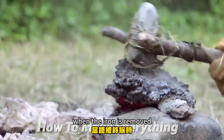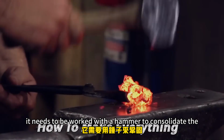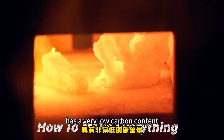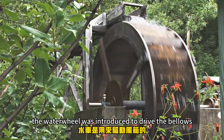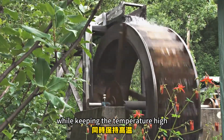When the iron is removed, it is in the form of this porous mixture of impurities and iron. It needs to be worked with a hammer to consolidate the iron, while the waste material is beaten off. The material left over is wrought iron, which, as we discussed before, has a very low carbon content. These bloomeries produce very small quantities of iron, especially before the water wheel was introduced to drive the bellows, which allowed the bloomery to grow in size while keeping the temperature high enough.